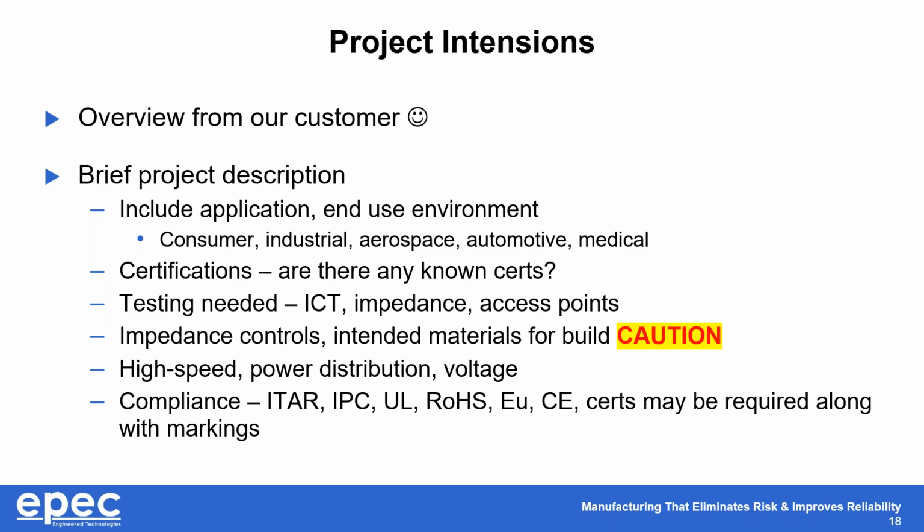So our intention on this call is to get an overview from our customer, get a brief description of the project, what it's going to go into, what the environment concerns are, if there are any, what your timeline is, if there are any certifications that are needed for the board to meet, if there's any testing needed that has to be done up front, if there's impedance testing, in-circuit testing, if there are any access points that are going to be needed after assembly. Impedance controls, intended materials that you have in mind to use.